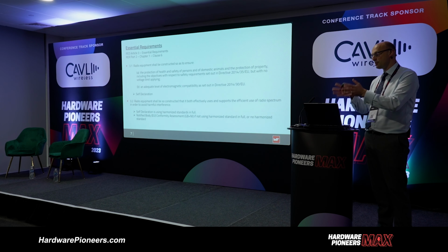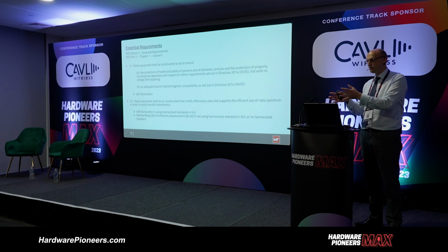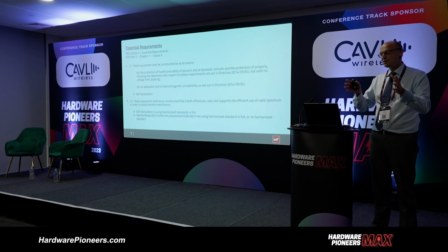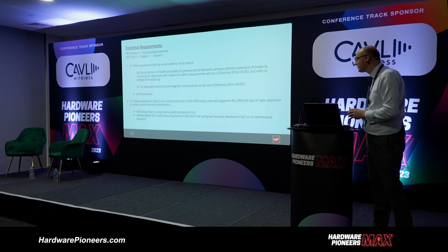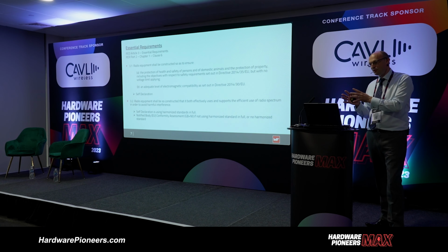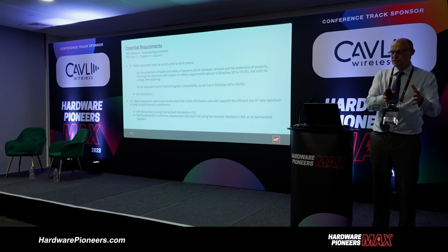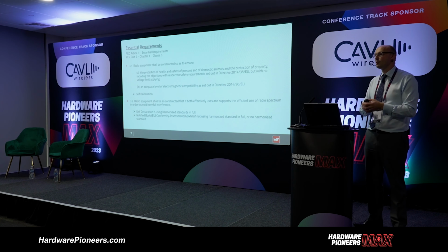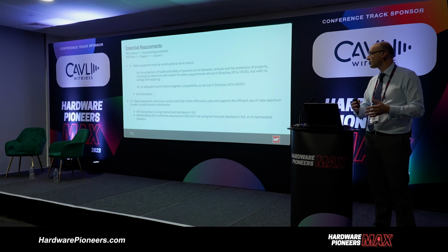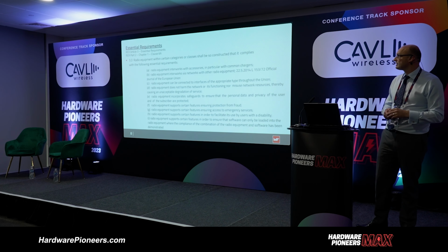So it could be that once again the pre-approved radio module has been tested or certified to a harmonized standard. As soon as you take that and embed it into your end product, that is what you're now certifying. If there is no harmonized standard, then this is where you use the likes of a notified body. So what we're trying to say here is that you can't just assume that if an RF module is CE marked, you can just import it straight into a product and still maintain that CE mark. As a manufacturer, you've got to look at what the end product is actually doing with regard to its functionality, the environment that it's being used in, and make sure you meet the correct standards.